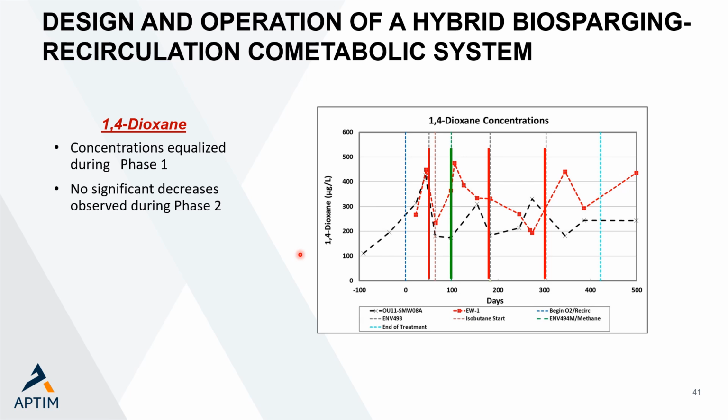So I believe if in that first bioaugmentation we could have decreased 1,1-DCE concentrations down into the low ppb range, we would have seen a very good reduction in all of the other contaminants, because that's what we saw in all of our laboratory testing. But we always had this background of 1,1-DCE, which was likely killing the bioaugmentation culture and any native organisms that likely would have come up to degrade the other contaminants.